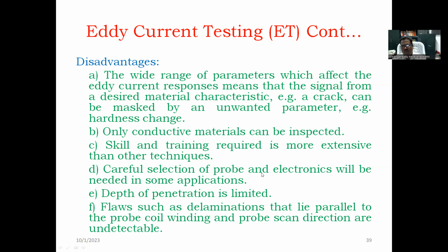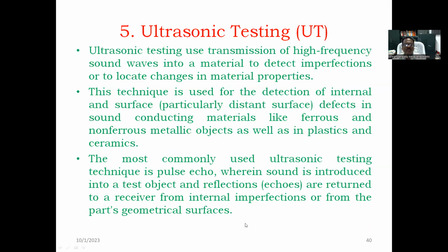Careful selection of probe and electronics will be needed in some applications. Depth of penetration is limited. Flaws such as delaminations that lie parallel to the probe coil winding and the probe scan direction are undetectable.